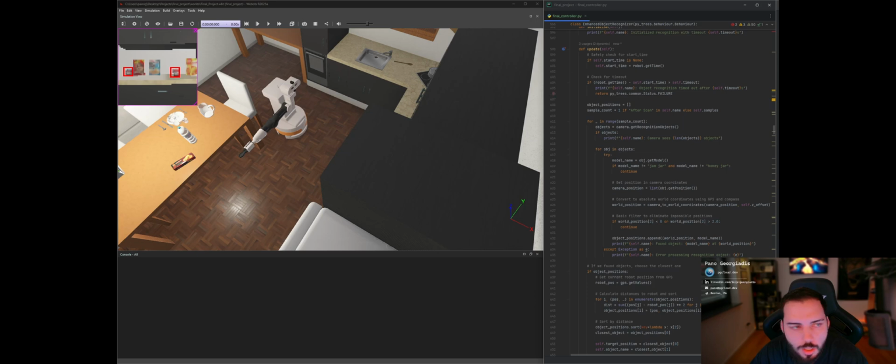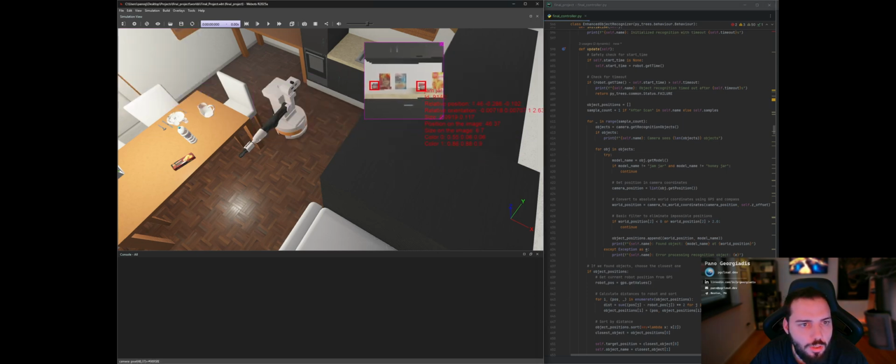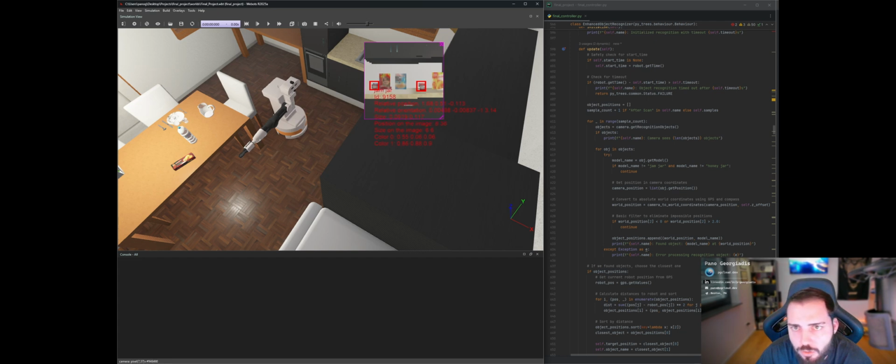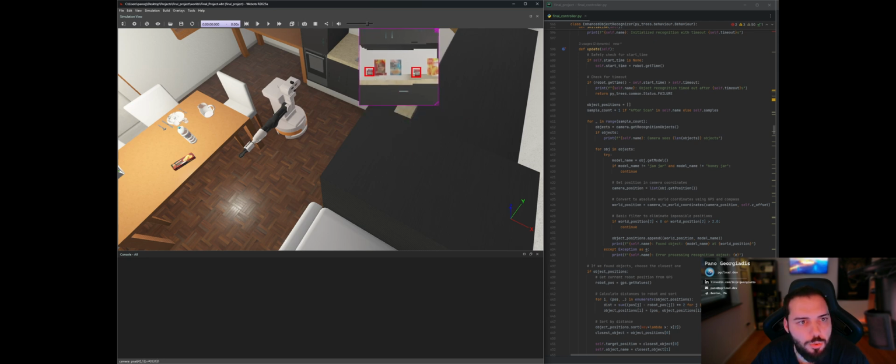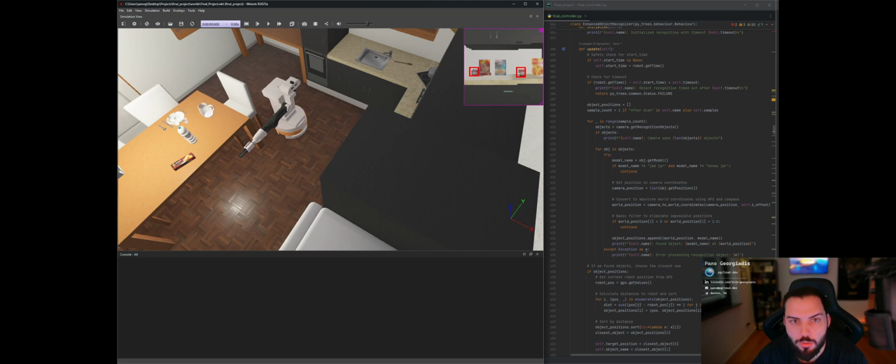And if you look, for example, on the camera, because of the enhanced object recognizer, we're getting the name of the object, its ID, relative position, and then color. You could also use object recognition with the camera that's mounted in the TIAGo robot for color recognition if you wanted to. I found it was easy, since we're just going after jars, to just go by the name of the object. If it is a jam jar, honey jar, things of that nature, then it would get recognized and put on the blackboard, and it would know, okay, we need to go there and grab that.